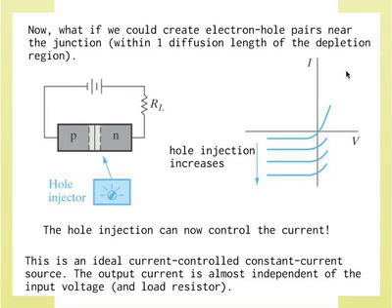As you increase the hole injection, you're changing that reverse saturation current. And by our good understanding of PN junctions, we know that the reverse saturation current should be independent of the reverse bias voltage. So you have a saturation operation, which means that now you can use that as a transistor. You have amplification and switching. Those are the two things for a transistor, right?